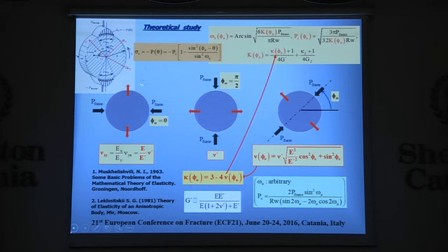independent of the orientation with respect to the x-axis, are elastically equivalent. So what to do here is to modify this expression in order to adjust it to our case, and to do this we start from the case when the external applied load is parallel to the planes of isotropy. Then we can obtain easily, from the data of the problem and the symmetry of the matrix of Hooke's law, the Poisson ratio corresponding to the dilatation normal to this compression, given by this expression.